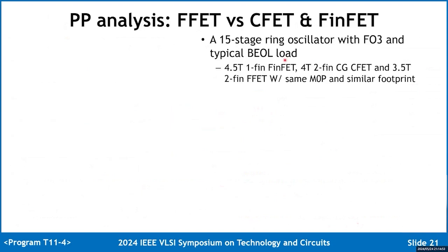Now we come to the power performance analysis. For power performance analysis, we use a 15-stage ring oscillator with fanout 3 and typical back-end-of-line load. For fair comparison, we choose FinFET, common gate CFET, and FFET with the same M0 pitch and similar footprint.